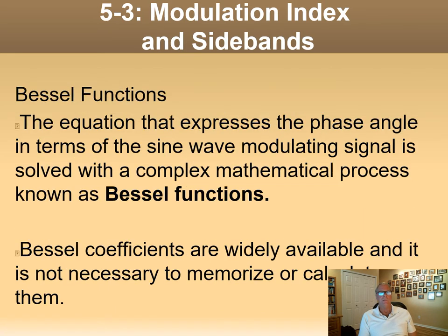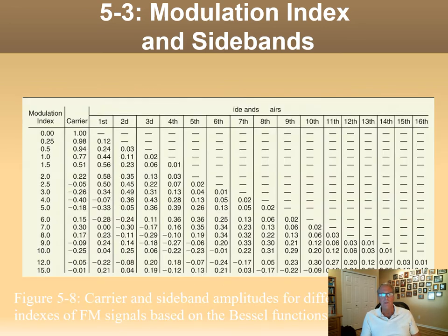So, Bessel functions. Oh, sounds scary. This is a set of equations that express the phase angle in terms of a sine wave modulating signal, but you have to use a complex mathematical process known as Bessel functions. Now, good news, that's the bad news. The good news is that we don't have to do any Bessel functions because they're all published in tables in terms of coefficients. So here's a Bessel function table.